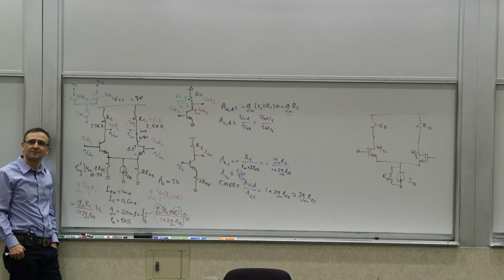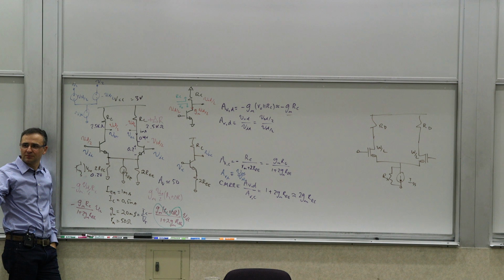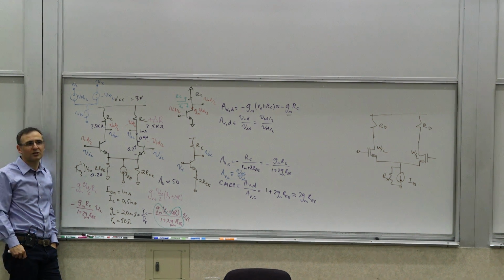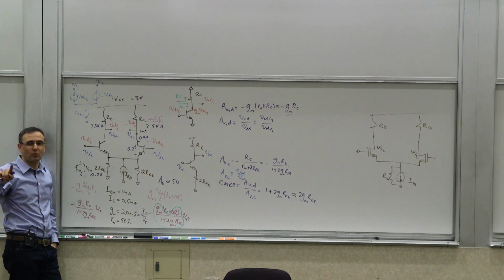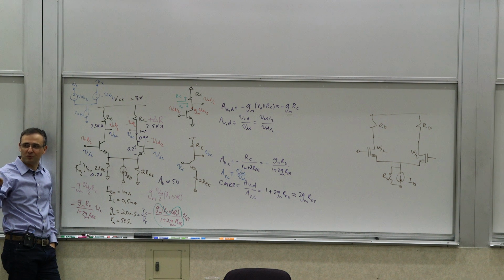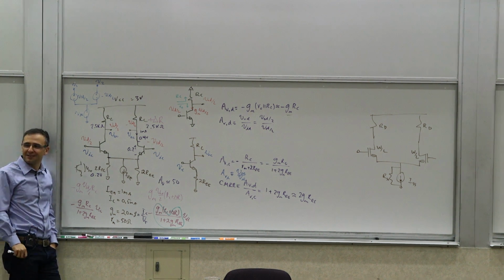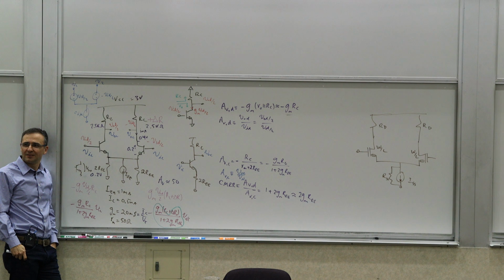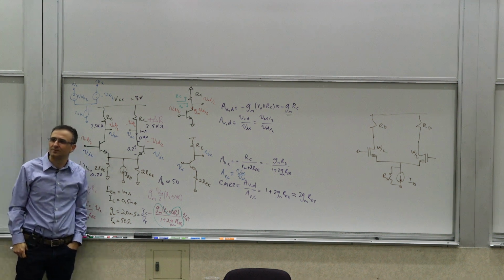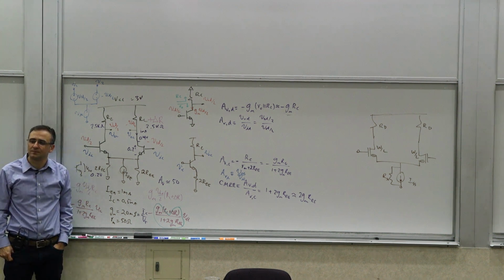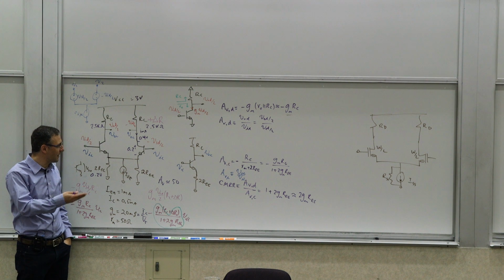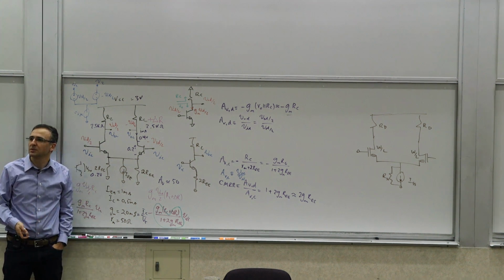Trade-offs. The smaller current will have lower power dissipation. I'm going to say the larger current will be more robust. Yeah, so both statements are good statements. Can you elaborate a little bit on how it would be robust? Like it will be less susceptible to changes in the base load. Okay, so it will be less susceptible to variations and changes. That's correct. Anything else?